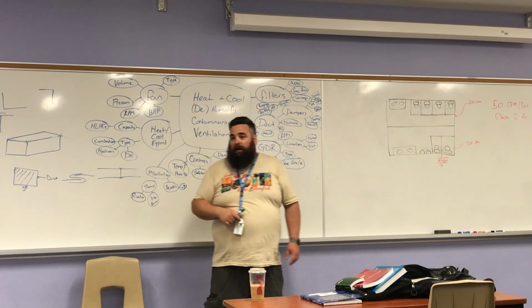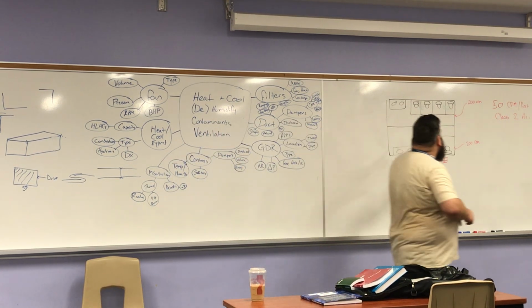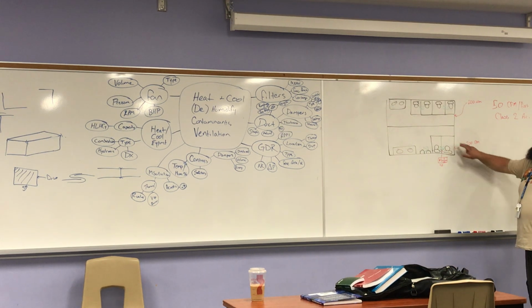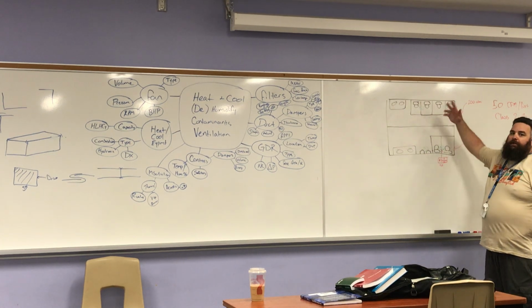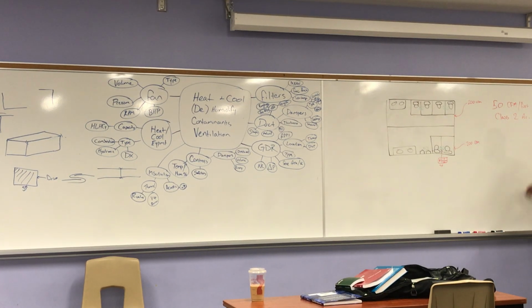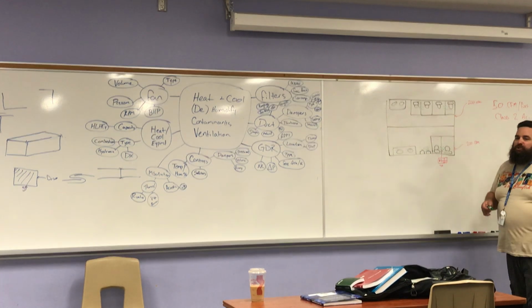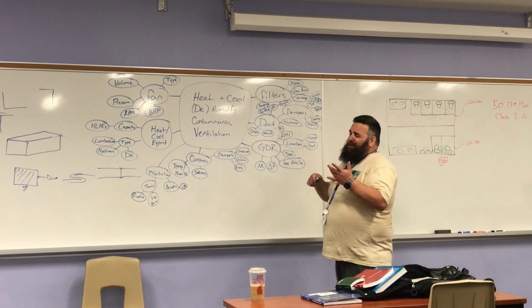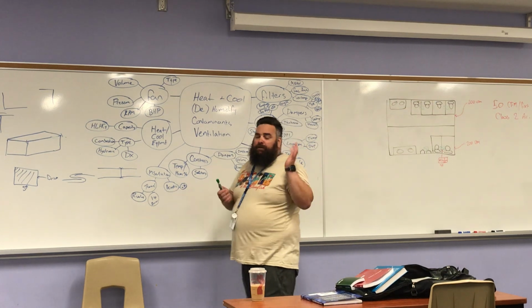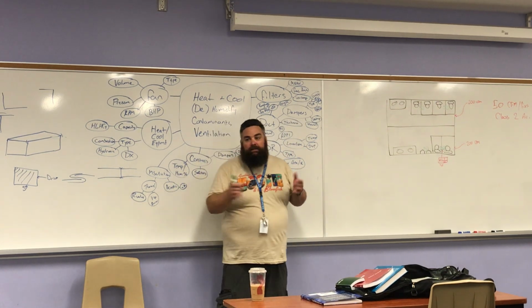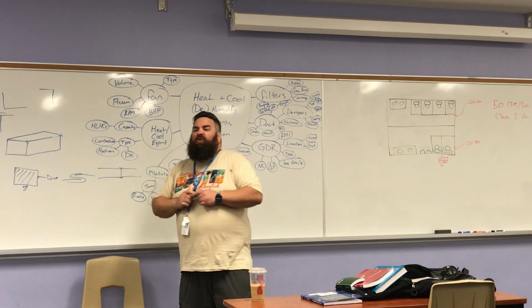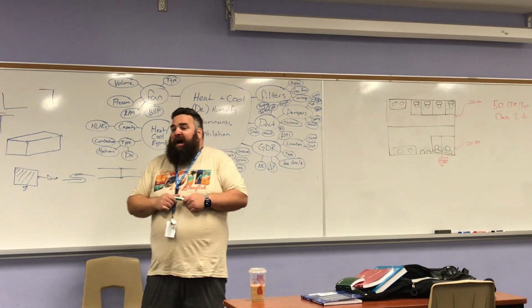What would the consequence be of going, instead of 200 CFM or 400 CFM total, if I went with 70, that would be 140, 280, 280 times 2 is 560, if I did that right. So 160 more CFM. What's the consequence of that? I'm probably not jumping up a fan size. They're just going to go a bit faster. My grills might increase in size a little bit, but they're not going to change in cost materially. The only real negative consequence here is the fan power.